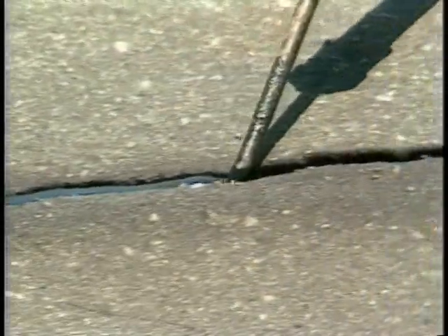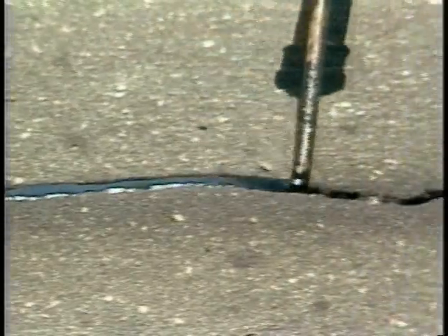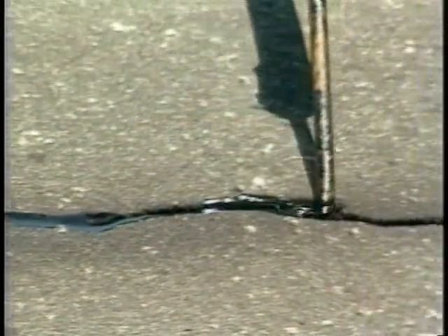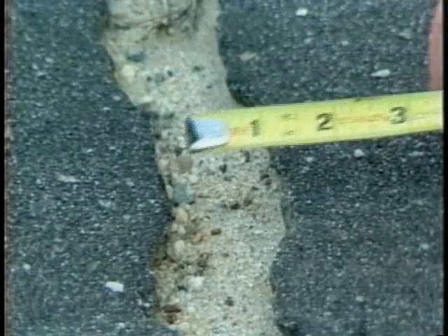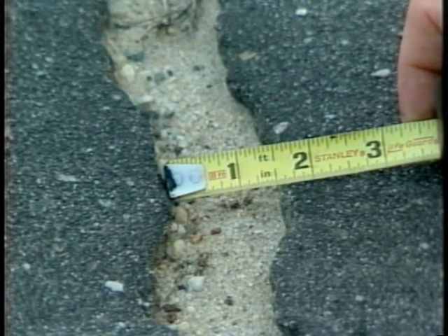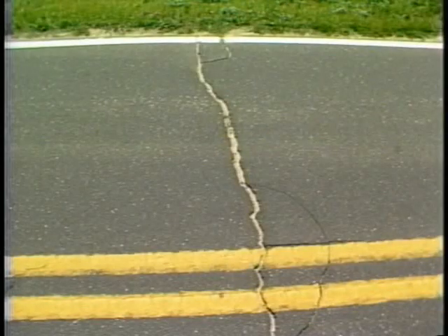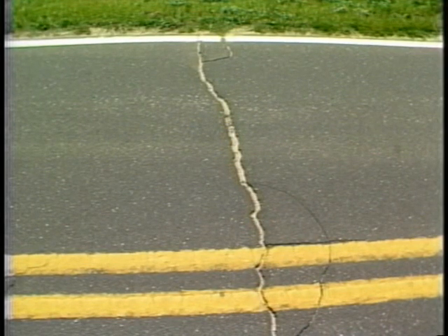Fill the crack to a level equal to the surface of the pavement. Do not overfill the crack, because this creates a buildup of material on the surface. It may be torn away during snow plowing and may cause a poor ride quality. For cracks wider than 1 inch in width, conventional crack sealing procedures will probably not suffice. It is suggested that the crack be cleaned and a lean sand asphalt type mix be inserted and tamped.